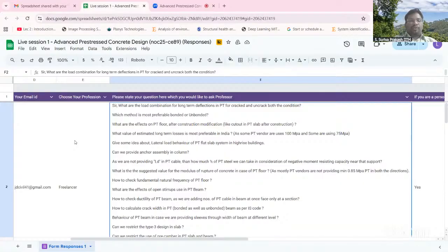unless you show in your calculations, you do all the calculations to ensure that it's not going to adversely affect, or your construction is not going to be compromised. That's what we do in external strengthening. When we go for strengthening, typically we take the anchor from the columns or shear walls, right? But that is because the structure is already there, we assess the condition, then we locate where the reinforcements are not there, and through that we drill a hole and then we put an external anchor.